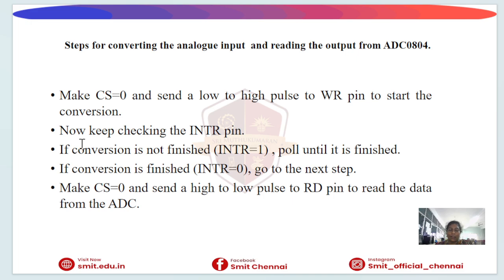So we write the binary equivalent, as in this diagram. This timing diagram shows when the write pulse is given, the duration of conversion, INTR going low, and then the RD pulse to read data. So this helps us understand the exact sequence of the signals.